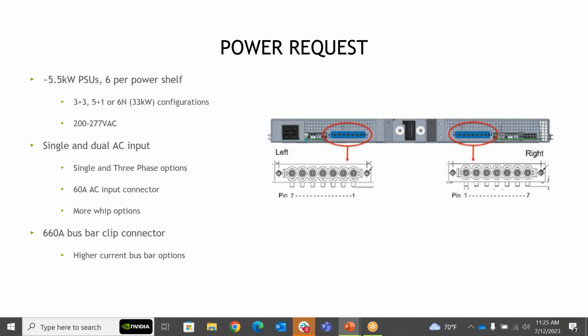Thank you, David. And Harry, thanks for bringing up the dynamic nature. We are doing things at different levels within the power infrastructure, really from GPU all the way to the grid. There are different knobs that we'll be able to turn at different levels, but in particular, the AC to DC power supply, the bulk capacitance, is the stage in a lot of these infrastructures that provides the energy for these very fast transients.